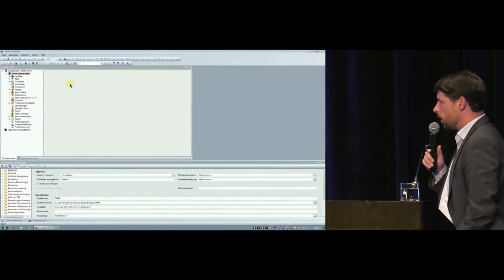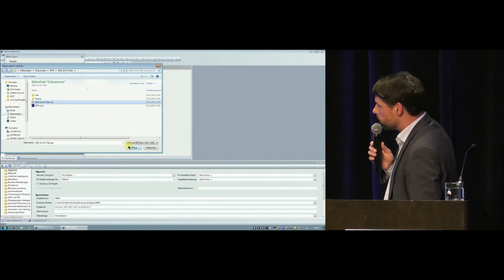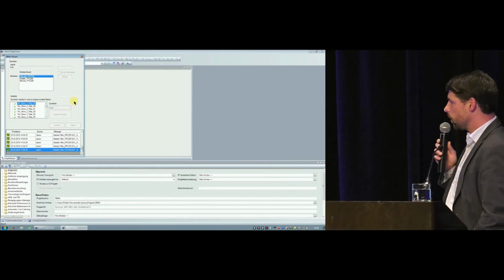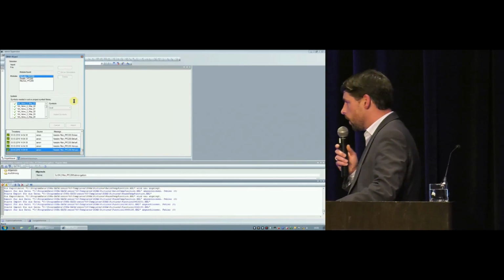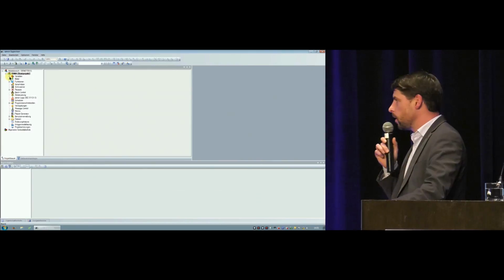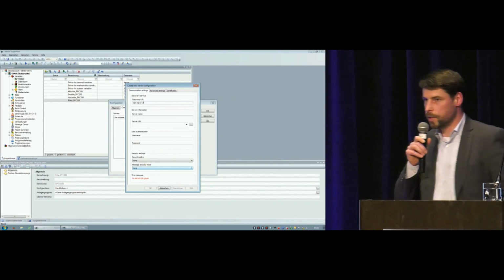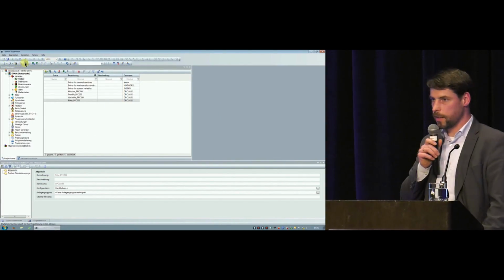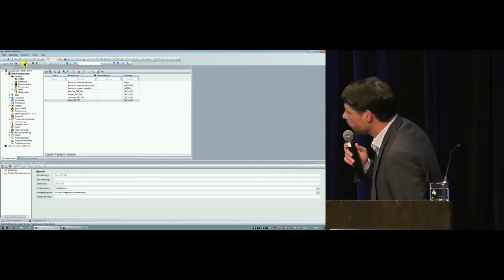Now the process production plan can be made, and this is the state where the MTP file is read in, and I've chosen this, and now all the variables are included, all the HMIs are mapped, and the services are modeled as phases inside the batch system. The only manual step is I have to add the IP address to the OPC UA driver, and when it's done, I can start the runtime and everything is fine, and I can use the controller as if it is the controller of the vendor. Now the runtime will start.